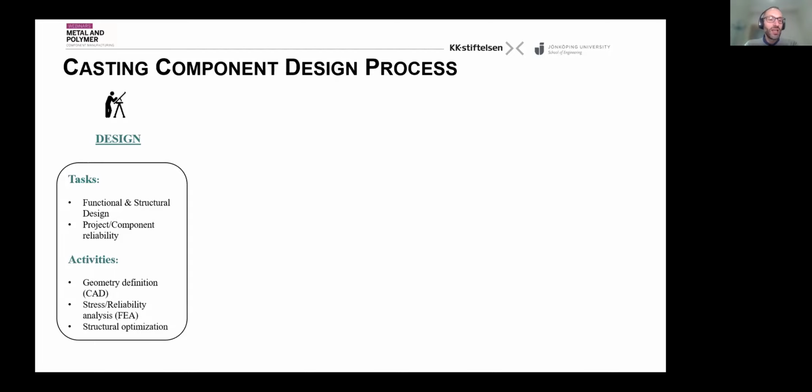of the component. And it can also use structural optimization, as Jacob mentioned, like topology optimization, where the material is put where needed, or shape optimization, where we change the shape of the components to get less stress, and also the geometrical optimization, for instance, when you optimize a radius or something like this. So at the end of the design,